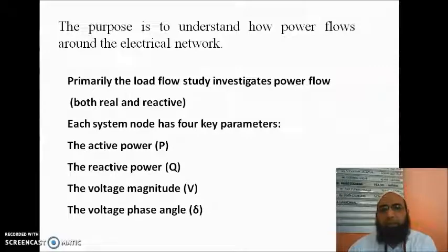So what is the purpose? The purpose is to understand how power flows around the electrical network. The whole purpose of load flow analysis is to know how the power flows around the whole network. Primarily, the load flow analysis investigates power flow. We have two types of power: real power and reactive power. Each system node has four key parameters: the active power denoted by P, the reactive power denoted by Q, the voltage magnitude by V, and the voltage phase angle by delta.